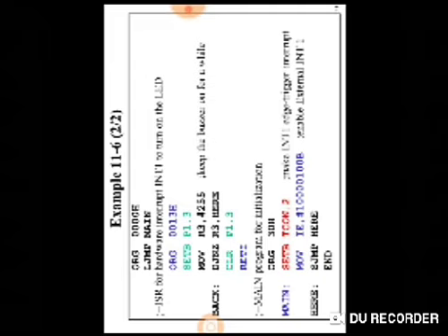Then the IE register is the main thing. The IE register has to be activated using 10000100. This enables the external INT1. You can refer to the IE register once again. Then you stop the program. So that's it. The LJMP will actually loop there itself.